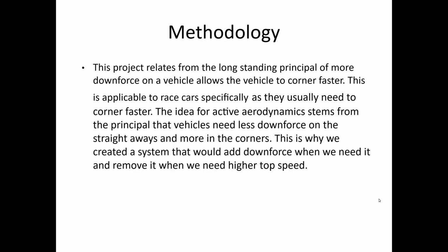This project relates to the long-standing principle that more downforce allows the vehicle or race car to corner faster. The faster a vehicle can turn around, usually the greater chance of them winning the race. So this is very applicable to race cars and our car in particular. The idea of active aerodynamics stems from the principle that vehicles need less downforce on the straightaways, because more downforce means that the vehicle has less top speed. So this is why we wanted to create an active system so that the driver, quote unquote, did not need to manually adjust this. It would simply do it automatically.